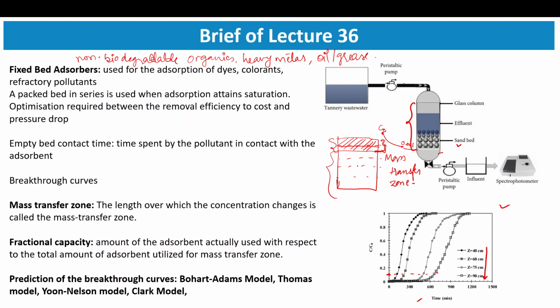Whatever adsorption takes place, it happens in that zone only. After the mass transfer zone, the packed bed has ended. Once that is utilized, you will start seeing the concentration of the pollutant in the outlet also. Let's say this is the inlet and this is the outlet. After some time you will start observing some concentration.